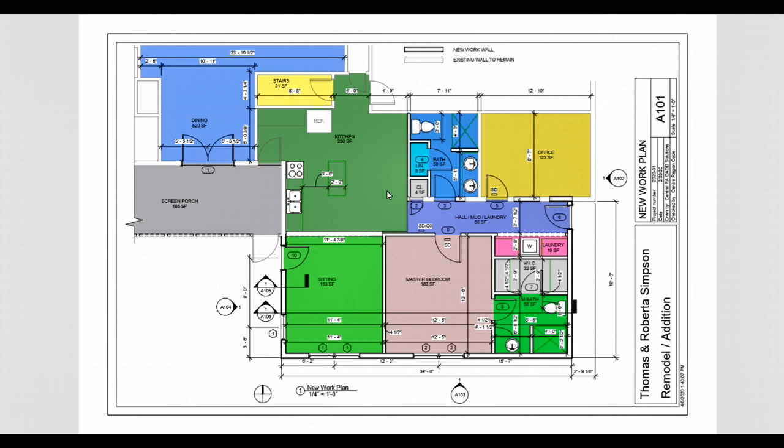So on to the next thing, room numbers and areas. So in room names, all these rooms have the actual room name and they show the area. And that's basically just something so the building inspector can very quickly and easily see what the total area is of each room. There are certain area requirements, certain minimum sizes for bedrooms and different things that you have to stay within, and they can very quickly and easily look at this and see that you're meeting those requirements.